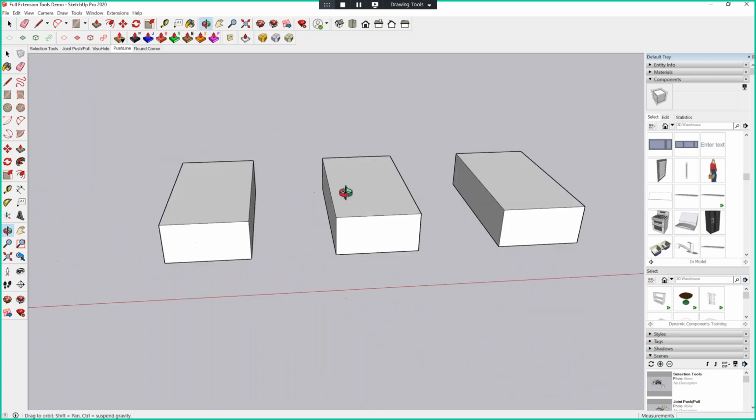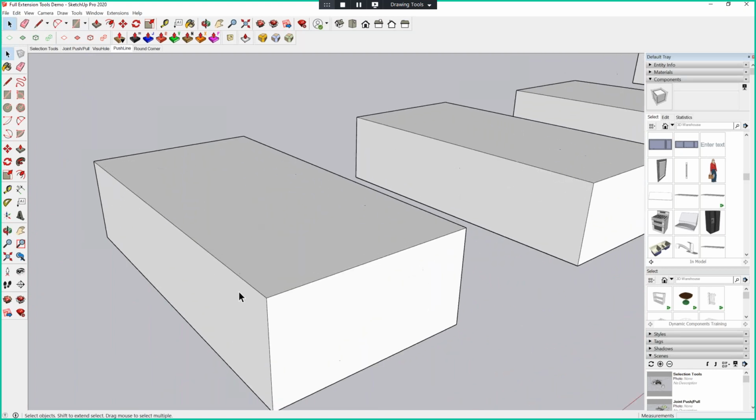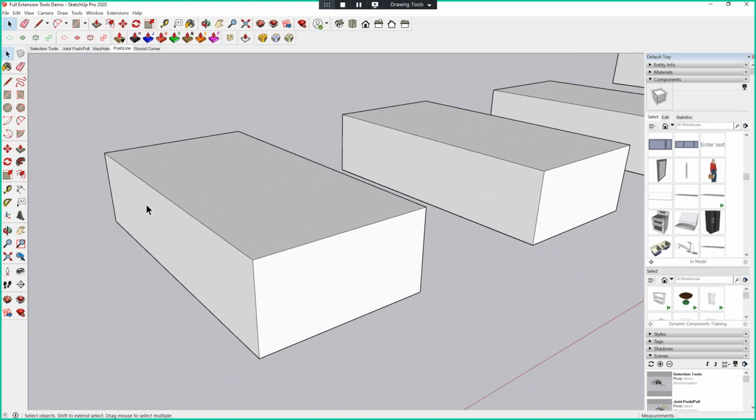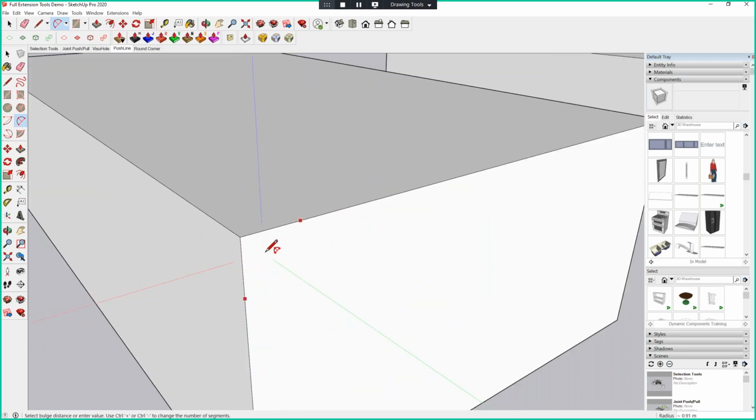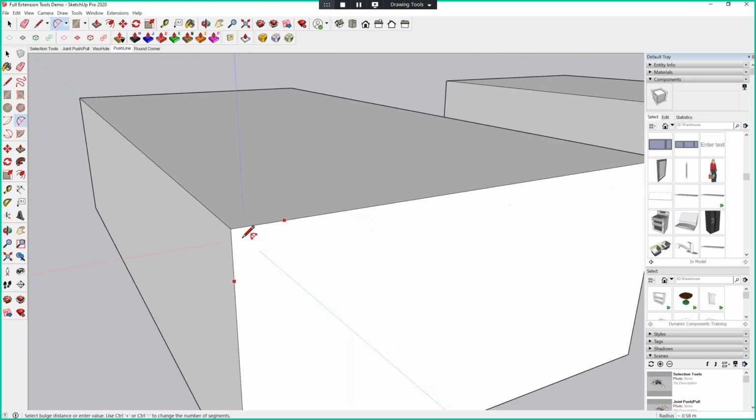The usual process of creating, let's say if you want to round this rectangle, after you have drawn this, you can do it through your native tools by using your two-point arcs. So let me click this face and bring it here. Once you see the on face reference, sometimes it doesn't show. Okay, let me click again.